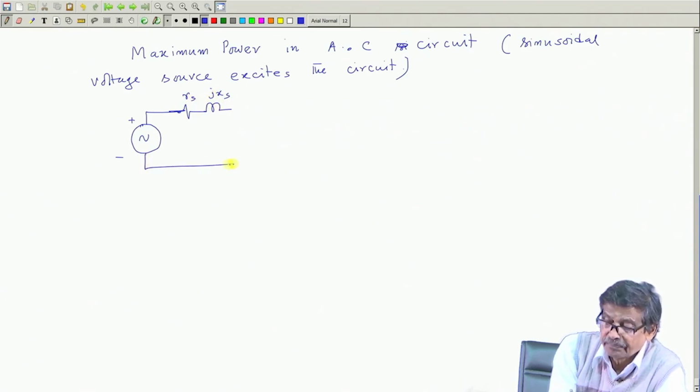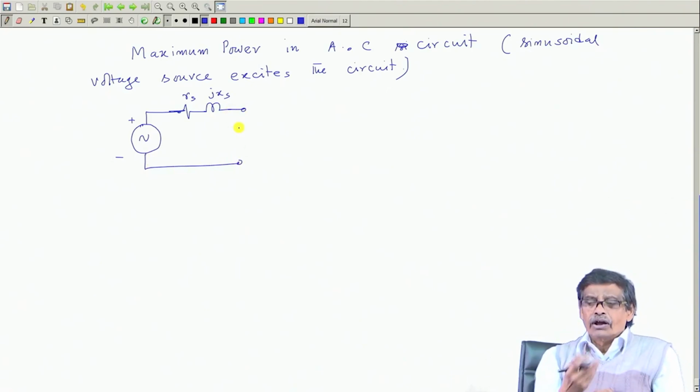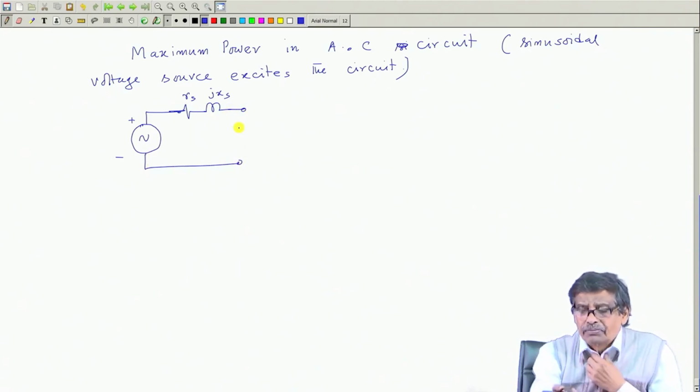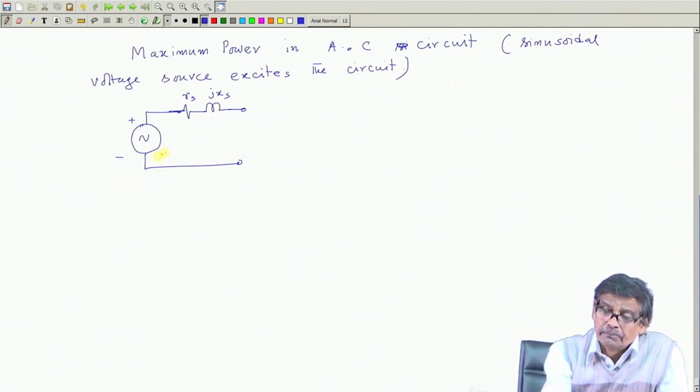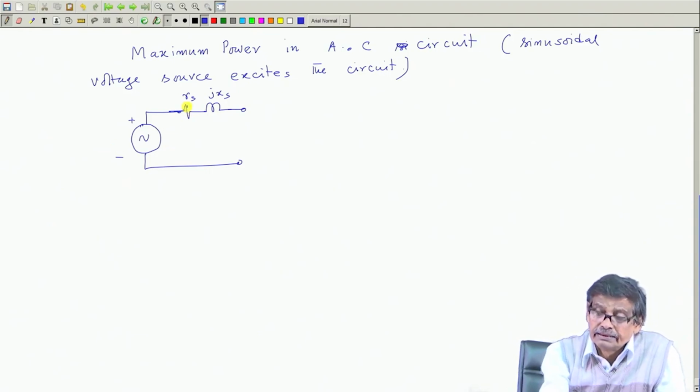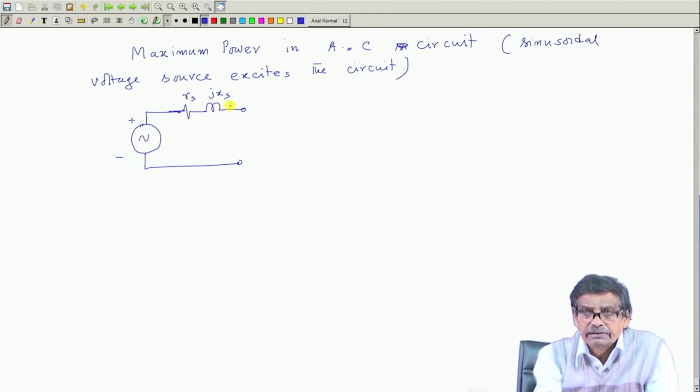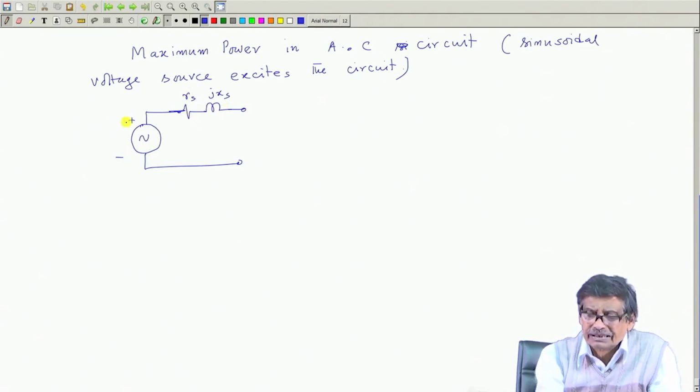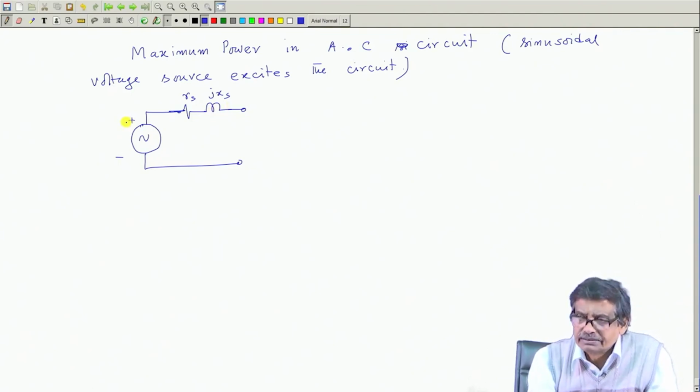Got the point? Because all generators are coils moving in a magnetic field, that can be modeled as a series impedance of winding resistance as well as reactance, nothing like capacitance: Rs and plus jXs, not minus.